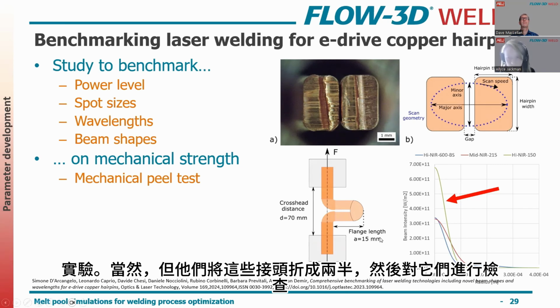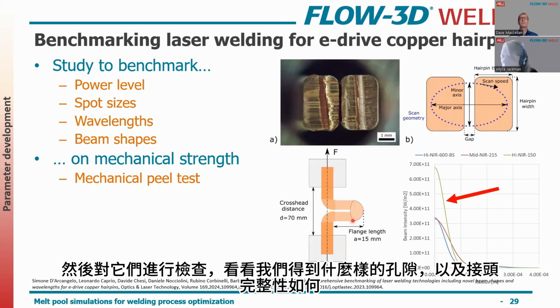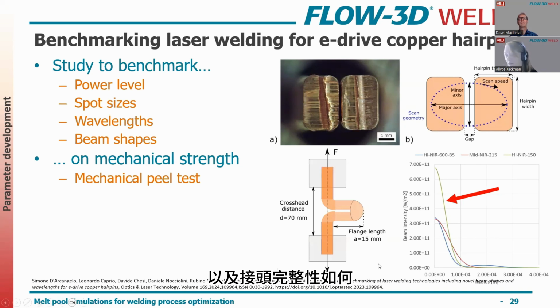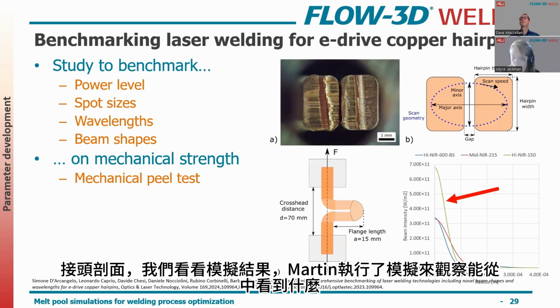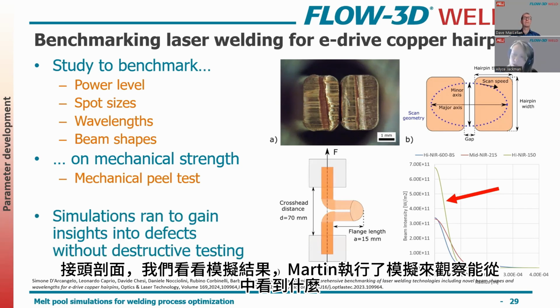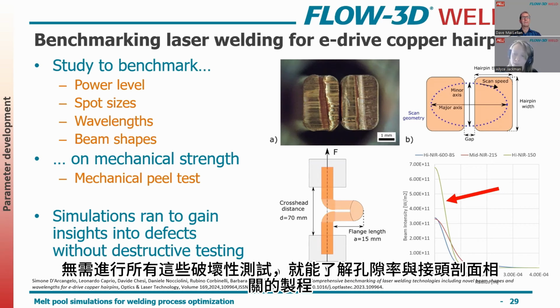So this is the copper, this is schematic, of course, but they were breaking these in half, and then they were looking into them to see what kind of porosity are we getting and what kind of joint integrity and joint profile are we getting. So Marcin ran simulations to see what we could see into this process about the porosity, about the joint profile, without doing all of this destructive testing.